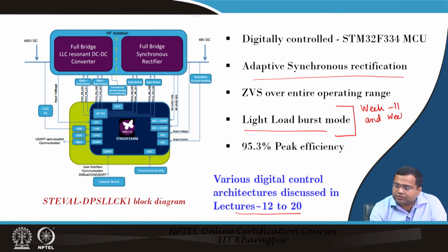So, which considers extensively light load control technique, digital control, how to synthesize, how to implement and synthesize using Verilog HDL, how to implement using FPGA. So, this technique will be useful. It is not exactly burst mode, but we have talked about constant on time, pulse skipping modulation, then adaptive on time control technique and also multimode technique.